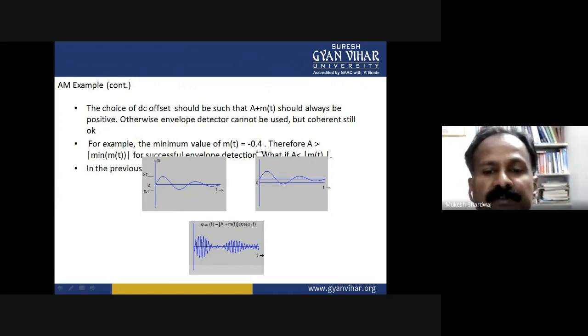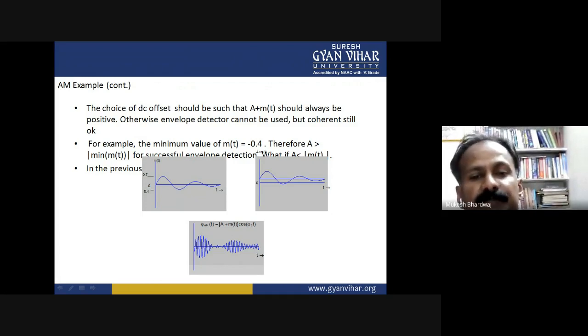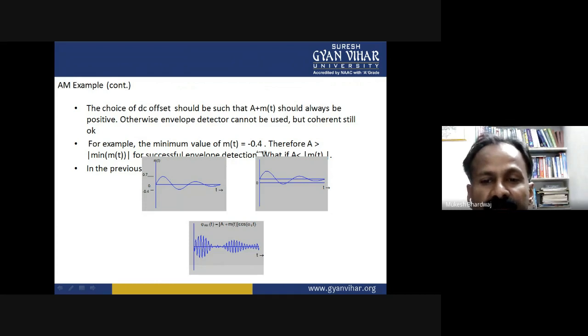Modulation, therefore, is the fundamental requirement of a communication system. Modulation may be defined as the process by which some characteristic of a signal, known as the carrier, is varied according to the instantaneous value of another signal, known as the modulating signal. The signals containing the intelligence or information to be transmitted are modulating signals. These modulating signals containing the information are also called baseband signals.